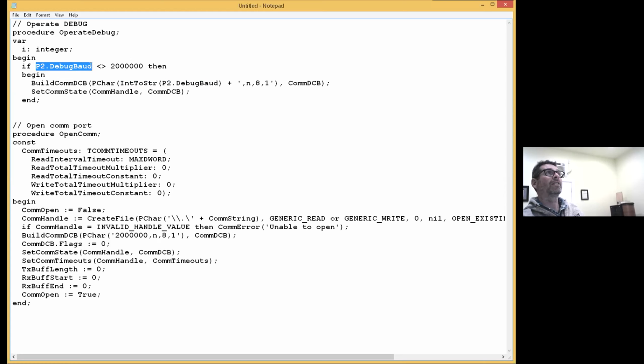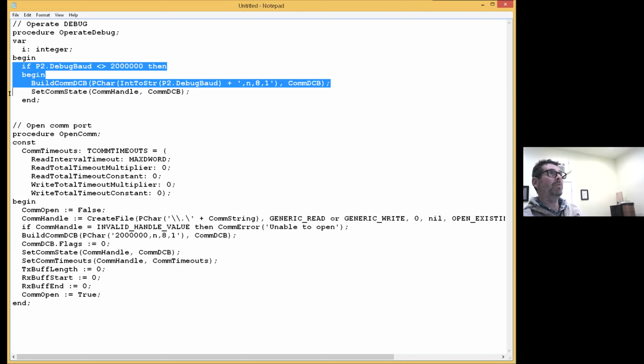Aren't you switching to it anyway? Sorry, you broke up. Say that again. Yeah, by build COM-DCB, you are setting it to 2 megabaud anyway. Yeah, now here's the initial one that I set the port up with. This is the first thing that I do. And then later I come back on the fly and ask, do we need a baud change? If so, do it.